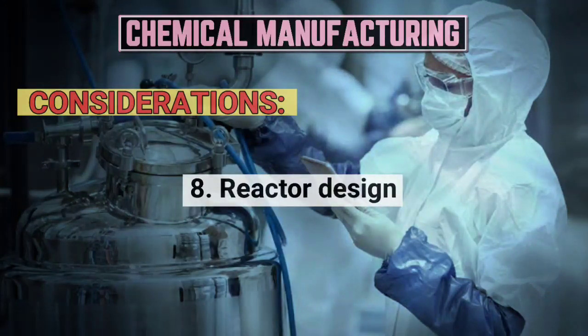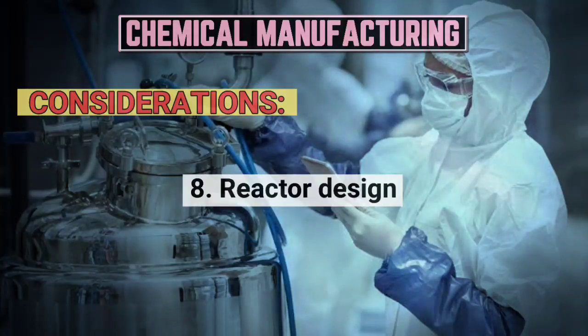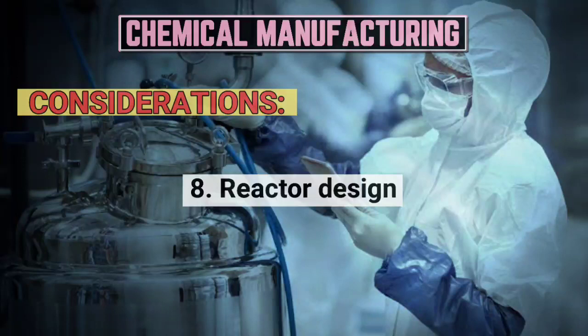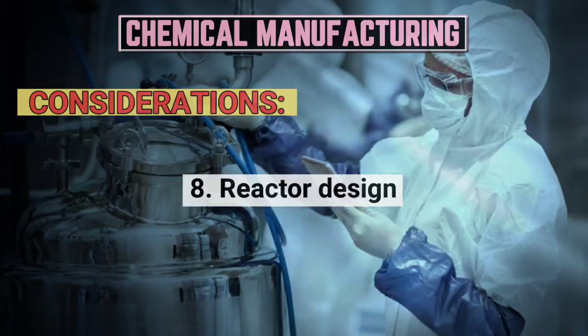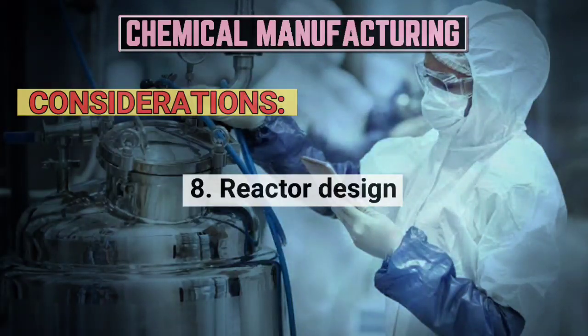Depending on that, you could look at the physical chemical conditions of the reactant at the reactor inlet. Then you could look at the size, what's going to be the overall size of the reactor, and its configuration and dimension of any internal structures and all of that. You also have to look at the exact composition and physical conditions of the product emerging from the reactor, and the operating pressure, just to optimize it.